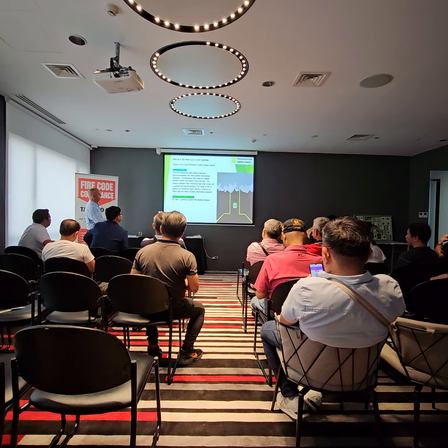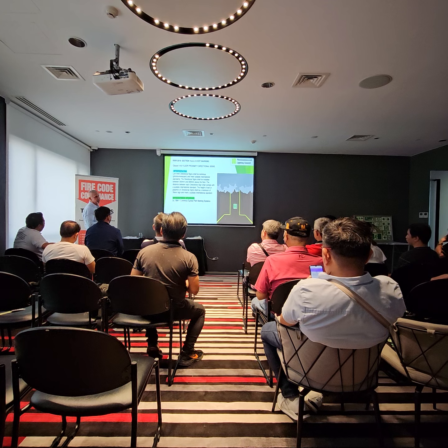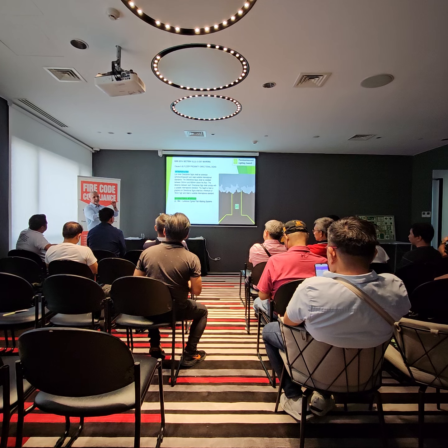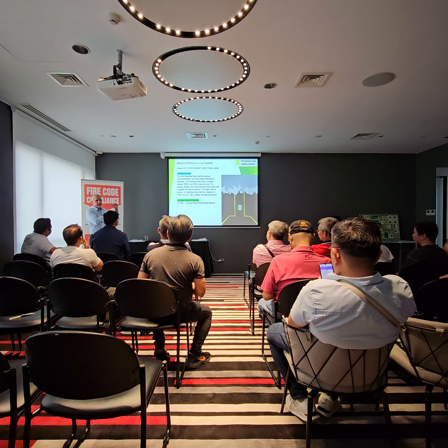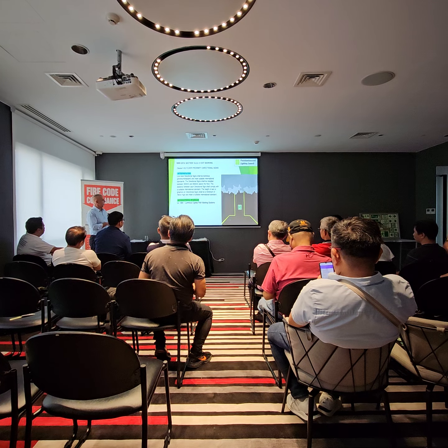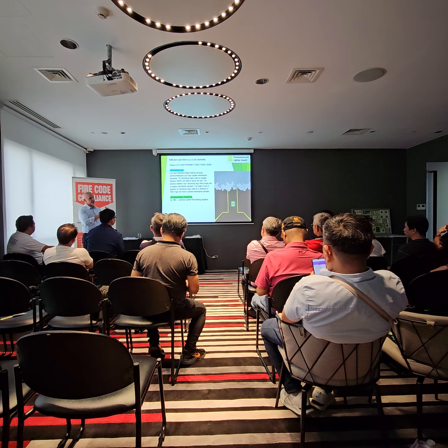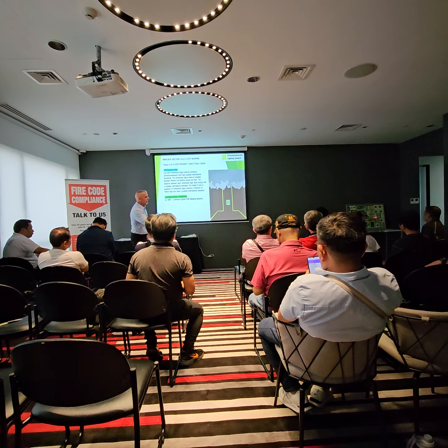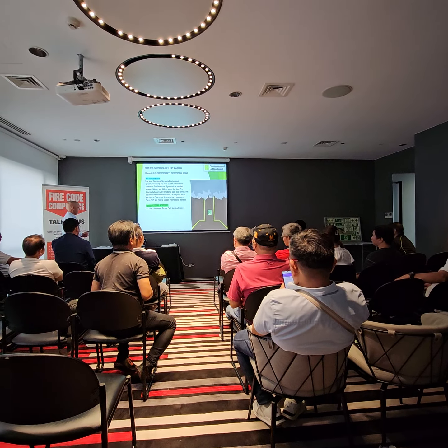Keith said there's some discussion with some places that everything has to be exactly 76 millimetres high. We said no other international standard says that. Let's say it's the minimum. Most would be looking for 100 millimetre high text or graphics for this sort of system. So we think that's where the 76 millimetres came from. So we say, okay, it's a minimum. There are UL 1994 signs there, and they're all 100 millimetres high. So all those sorts of things we believe would meet that requirement.